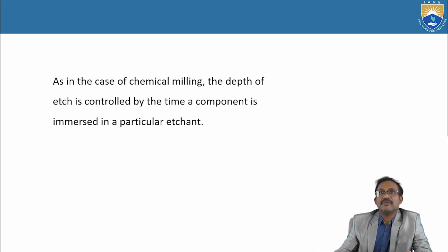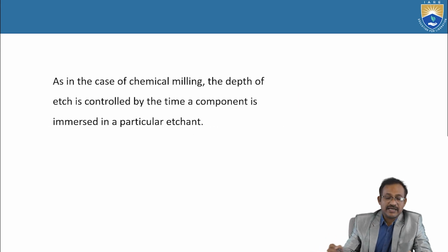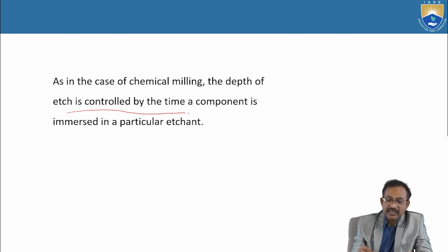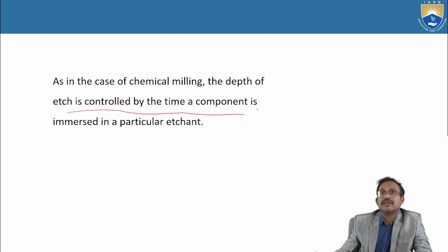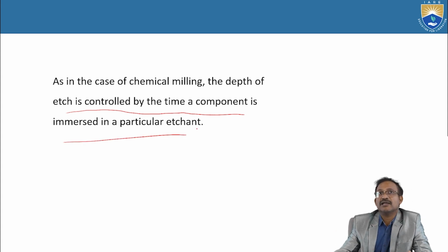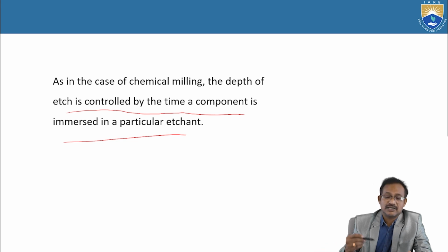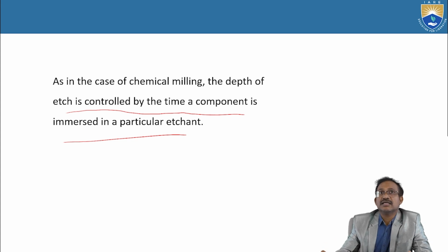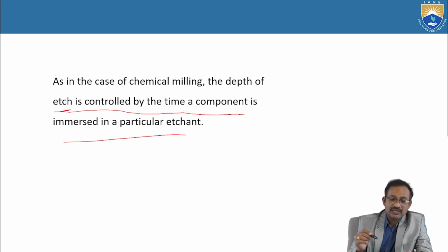As in the case of chemical milling, the depth of etch is controlled by the time a component is immersed in a particular etchant. So how much time we are etching is a parameter here.